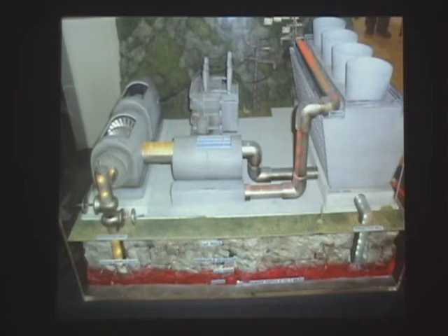Once the superheated steam's energy has been spent in the turbine, the saturated steam passes through a condenser and becomes a liquid which can then be pumped into a cooling tower and then back into the earth through a reinjection well. Although reinjection may not make the energy source renewable, at least not on the scale of a human lifetime, it helps the earth maintain stability and keeps the superheated steam's temperature from falling as rapidly as would be the case without reinjection.